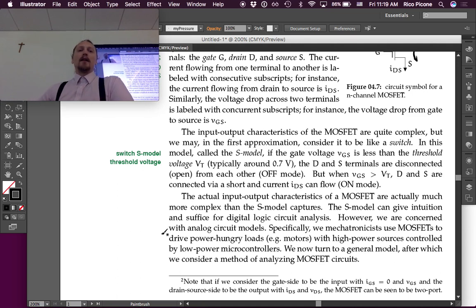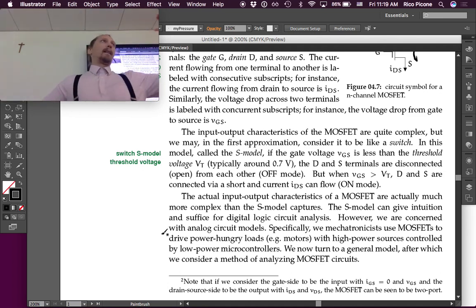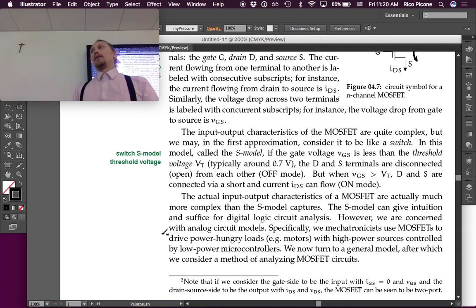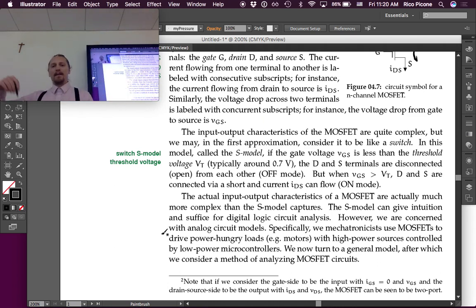Our microcontrollers allow us to put out an analog voltage at any level we want. But the thing that sucks about a microcontroller is that it can't output very much power. It might have 3 or 5 or 10 analog outputs, but they can't supply very much current. They can supply voltage in a range like 0 to 5 or 0 to 10 volts, but the current draw can't be very large, otherwise it can't supply the power.